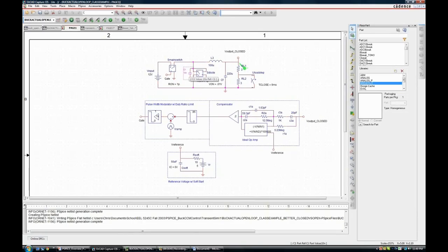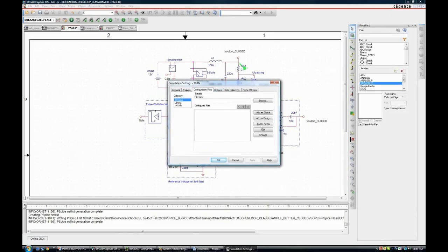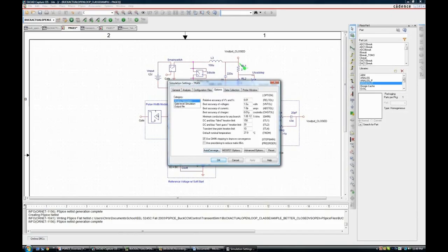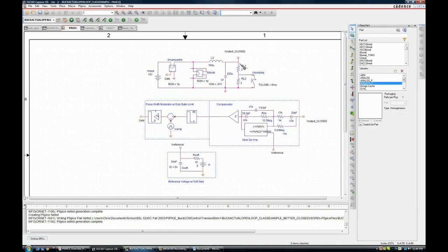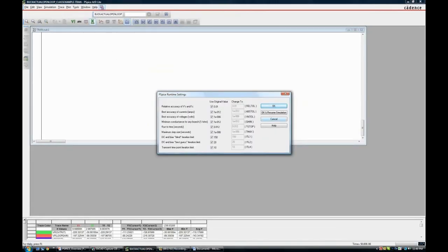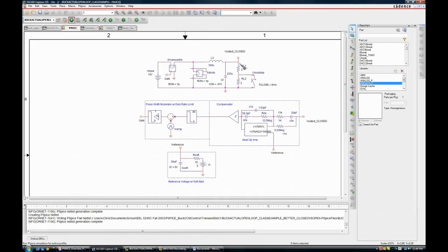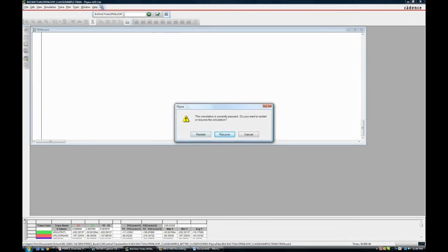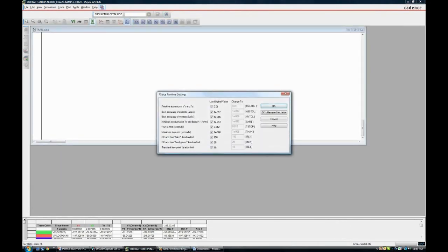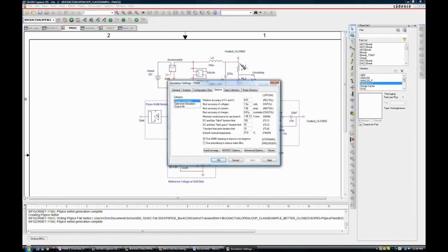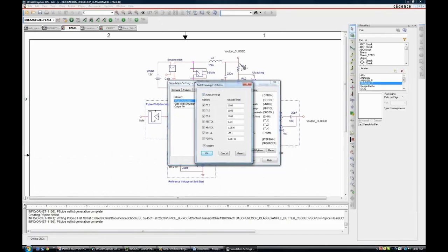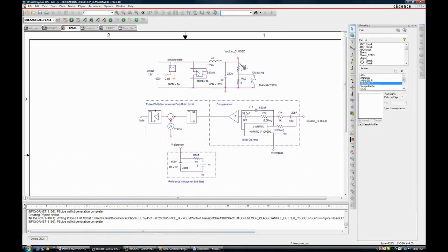I can take this guy out. Let's take it back out and actually run it without autoconvergence just to confirm that the simulation fails to converge. And we have our fail to converge. I can push it again just to make double sure. Restart the simulation. And of course it fails to converge again. But I can go in here and click auto convergence and do OK.